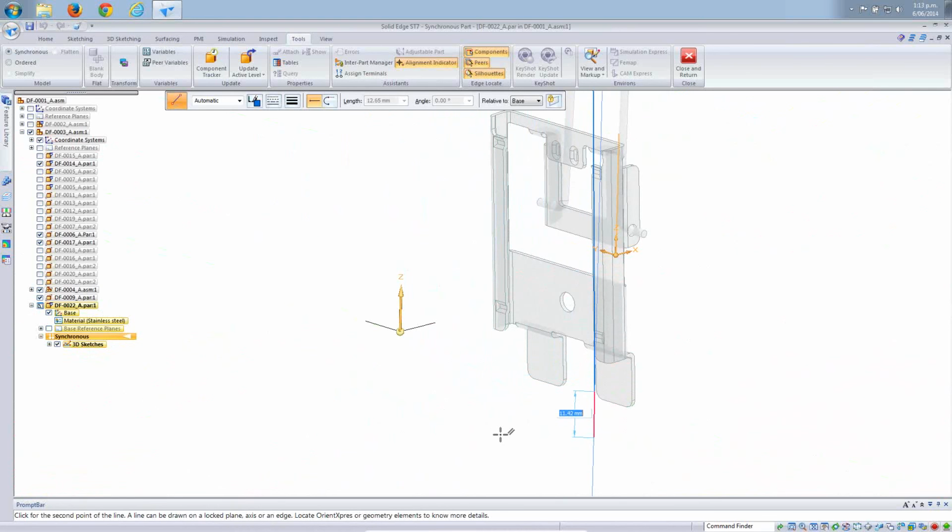So press Z once, and the next element that I'm creating will be parallel to the X axis, or if I press Z again, it'll be the Y axis, and it quite nicely filters out, so it's clear exactly which axis it is that I'm creating this geometry against. And again, I don't have to see the axis to be able to do that, because next to the mouse I've got a little green Y arrow. Let's set a distance on that and then click to place. Z a couple more times and I'm creating geometry parallel with the X axis.